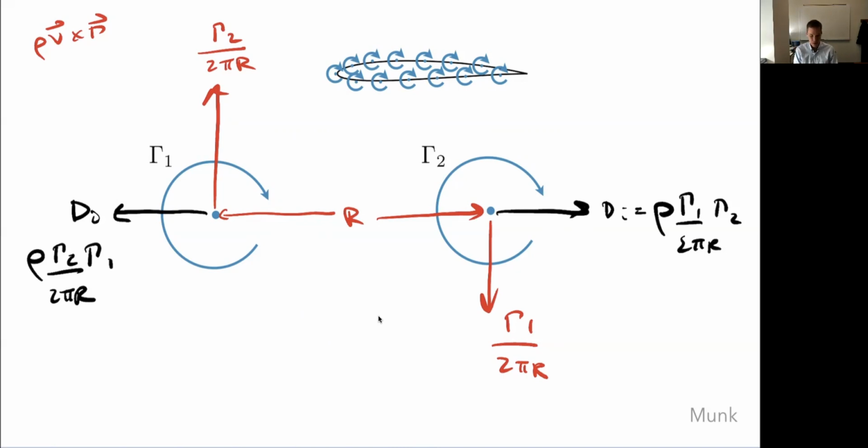But it turns out for computing induced drag, this still works, still gives us the right answer, because all these bound vortices will always cancel out. The contributions to each other, the sum will always cancel to 0. So actually what we've done will still give us the right answer, even though the model is a little bit flawed. It actually does still work. And Munk was the one who showed this idea of these bound vortices canceling.